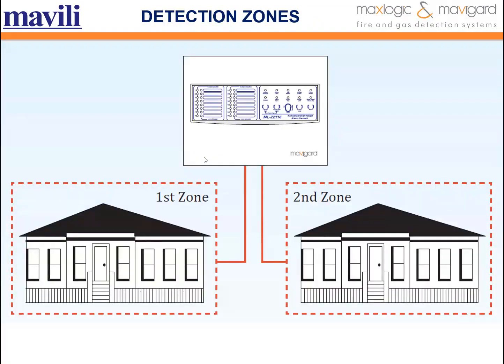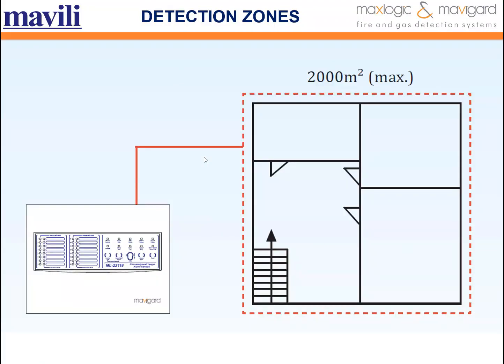Let's come to detection zones. In the fire alarm project, the building should be divided in the detection zones. Thereby, the fire alarm call points can be found easily via zone principles. A single area should not exceed 200 square meters or contain more than 32 detectors, or a search distance of more than 60 meters from the point of entry into the zone.